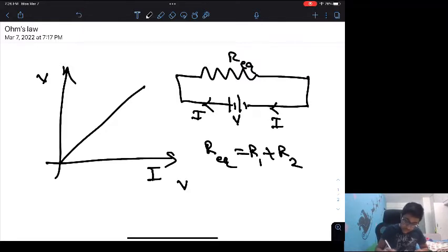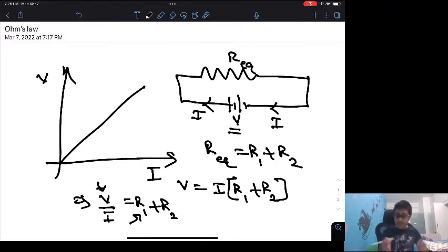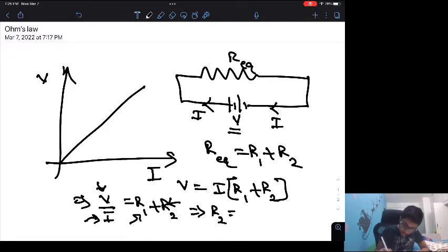Applying Ohm's law, we get the total voltage equals I times (R1 plus R2). But on rearrangement, we get V over I equals R1 plus R2. Now look at, we already know R1, we already know V, the voltage that is provided by the digital pins, or by the power rail in this case in the Arduino, is 5 volts. We can find out I in a clever way, and we need to find out R2. On rearrangement, we get R2 equals V over I minus R1.